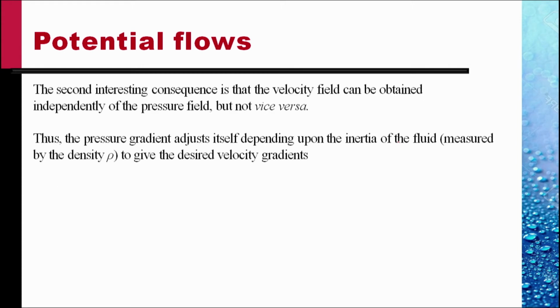The second interesting consequence is that the velocity field can be obtained independently of the pressure field, but not vice versa. We cannot solve the Euler equation to obtain the pressure field without knowing the velocity field. But we can solve the Laplace equation to obtain the velocity field without dealing with the pressure field.